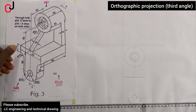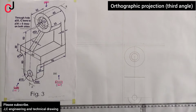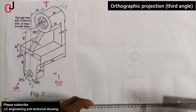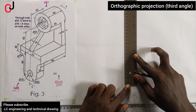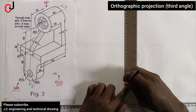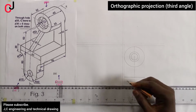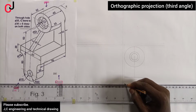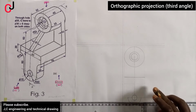Now from our side view, you can see that we have 20 millimeter downward, so we'll measure 20 millimeter, then we indicate the point, and then we'll project the point to my left, the construction line over there.